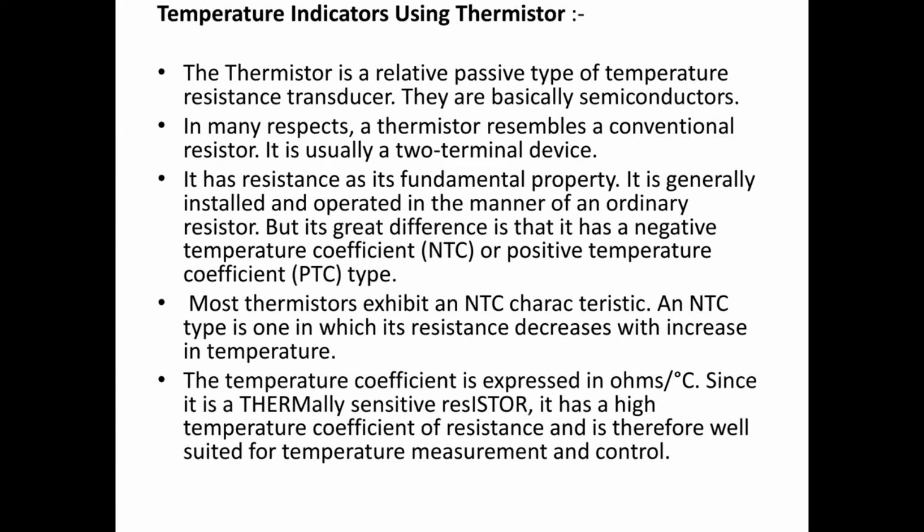Most thermistors exhibit an NTC. NTC means that as the temperature increases, resistance decreases. The temperature coefficient is expressed in ohms per degree Celsius. Since it is a thermally sensitive resistor, it has a high temperature coefficient of resistance and is therefore well suited for temperature measurement as well as control.